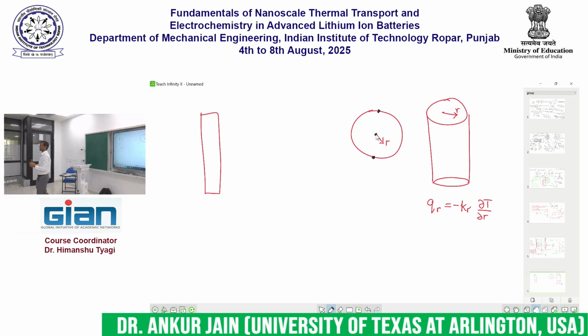The problem with that is that if I drill a hole in the cell, the volatile electrolyte in the cell will evaporate and it's not really a cell anymore, right? This lithium ion cell is a hermetically sealed system. I cannot possibly drill holes in. If this was a copper cylinder, sure, absolutely, that is exactly what they would do. You would drill a thin hole, put a thermocouple in the center. In fact, you'll place multiple thermocouples here, here, here and there. But that I cannot do with a lithium ion cell. The only radial location that I have available, unfortunately, is the outer surface.